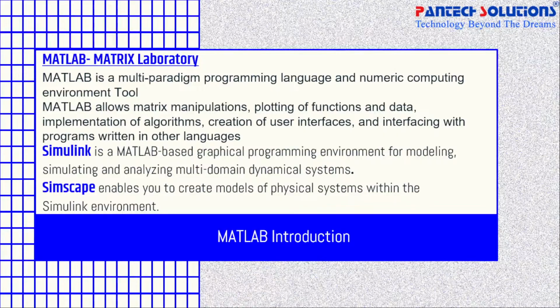In the Simscape environment, we develop the physical environment. In Simulink, we can only transfer signals from block to block. In the Simscape environment, we can transfer energy. For example, if you are using a thermal block, we can transfer that energy from block to block. That is the main use of Simscape. What types of blocks are involved, how we develop them, where we start, and how it is involved in our EV project, we can discuss from scratch.